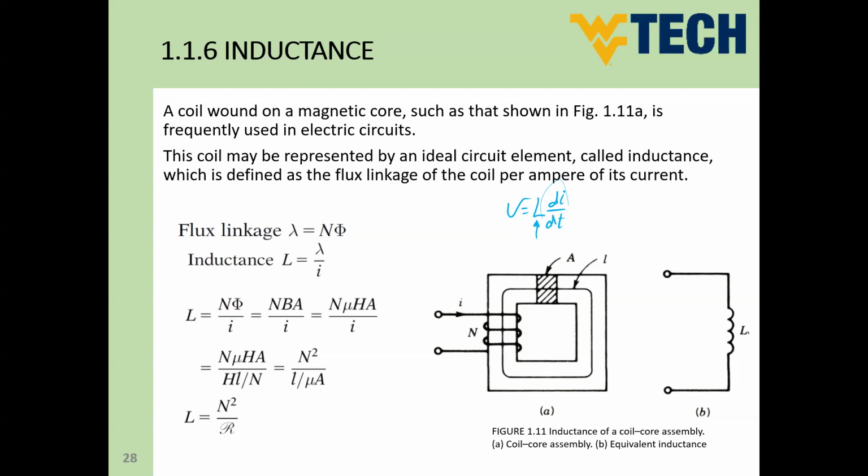This is the real inductance. Also, you may have what's called stray inductance. Stray inductance is not like a wound inductor, where you take some wire and a magnetic core and make a winding with N turns. But in any electrical circuit, guys, the current flowing in any wire will create a flux around this wire. So there will be an equivalent stray inductance. It's like a virtual inductance. It's not a real inductance, but it has the effect of an inductance. But the virtual or stray inductance has very small values, in nanohenries or sometimes reaching small microhenries in our circuits.